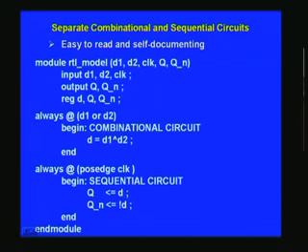And once you have just two blocks, always block. We'll come to this statement a little later. This is an always block which you are once again familiar with. This is just a combinational realization. Whenever D1 or D2 changes, for example, if D1 was 0 earlier and now it changes to 1, or let us say D2 was 1 earlier and now it changes to 0, only in the event of a change occurring will this be processed.